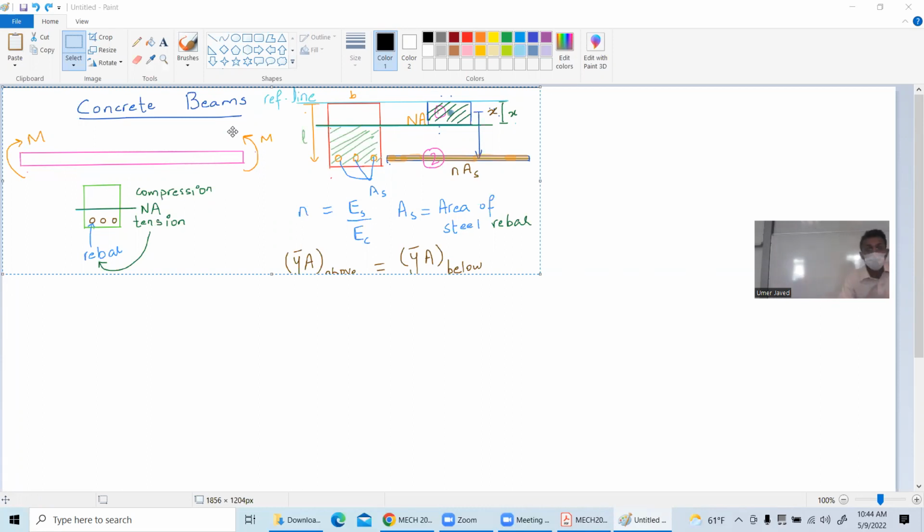Okay, so let me tell you what exactly we are about to do. Look, using concrete for a beam is very good, right? Why? Because you can easily transport concrete to any level of the building, in a semi-liquid kind of form. You can make beams with it. Life will be beautiful. The only problem with concrete is that it is exceptionally good in compression, but in tension, concrete is not good, right?